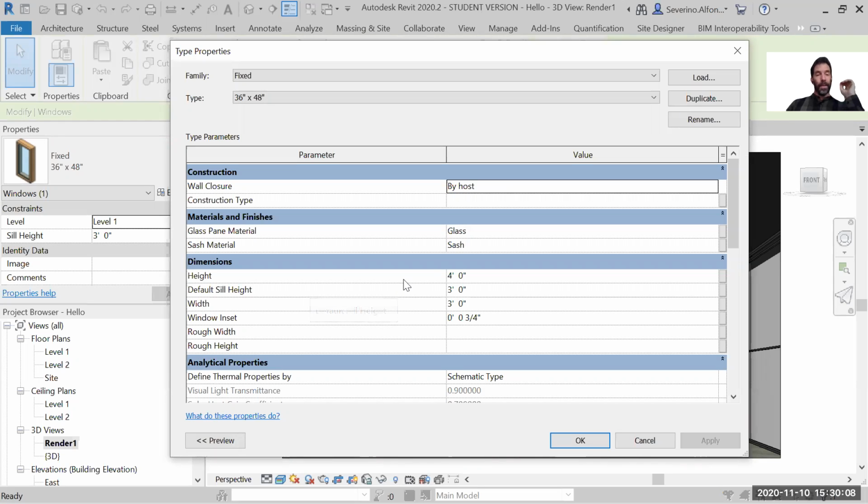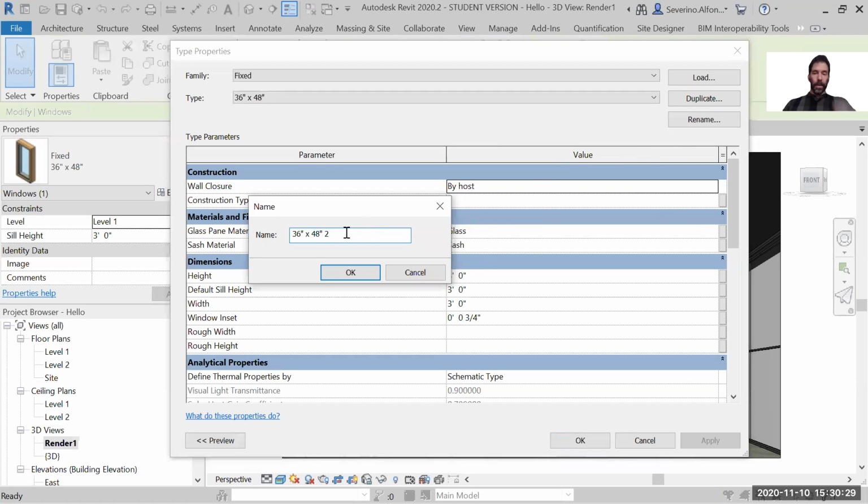Before you change any material in a door, in a window, even if you're only changing the material, you should duplicate, because you're changing the standard generated automatically by Revit, and you're declaring a new type. So I would always recommend to say duplicate, and you can even keep the size if the size doesn't change, and then say, I don't know, whatever it is,